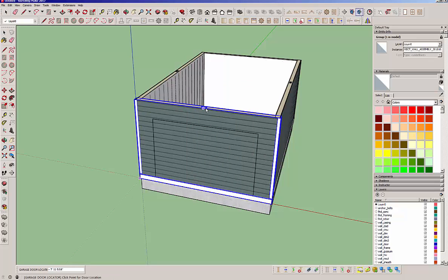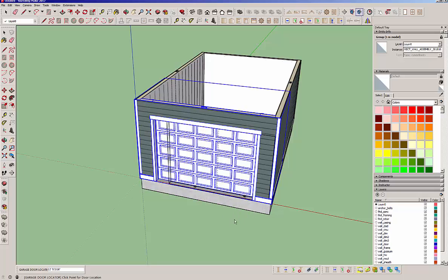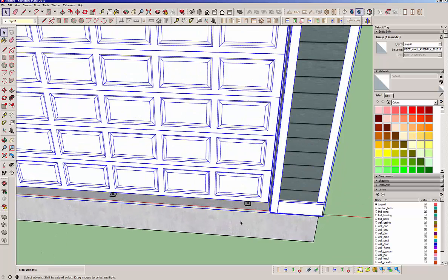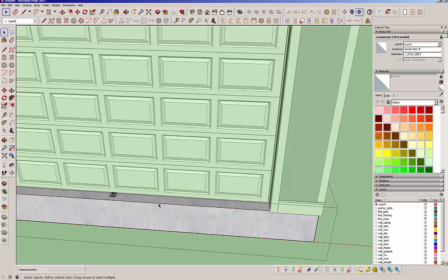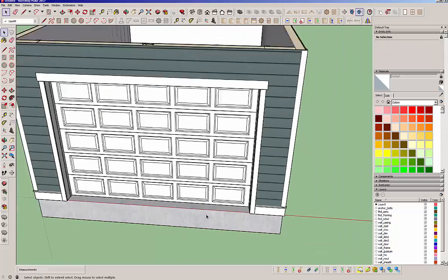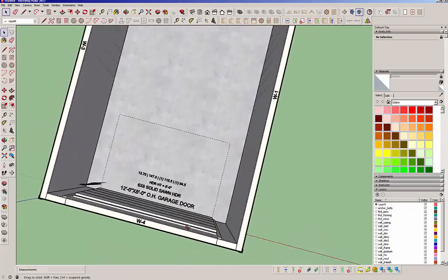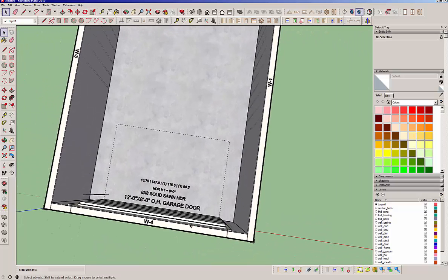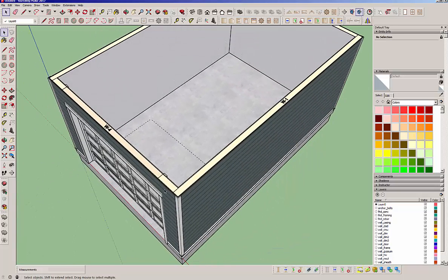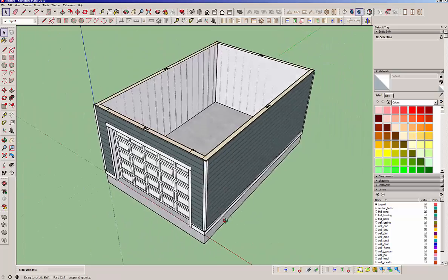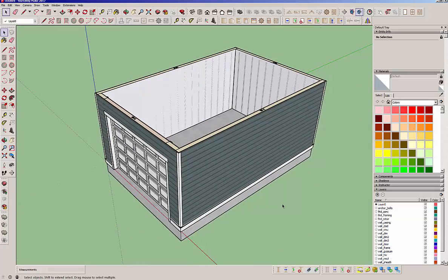And again, all of these parameters you can set after the fact. It's all parametric. Okay, and you can see we've got some anchor bolts here that are out of place, so we're just going to go ahead and delete those for now. Now remember that anything that you do manually in these plugins, the plugins are parametric, so when you refresh any of these wall panels, any manual changes that you made will be blown away. So typically you don't want to do a lot of manual changes, but if you do, then you need to keep that in mind.